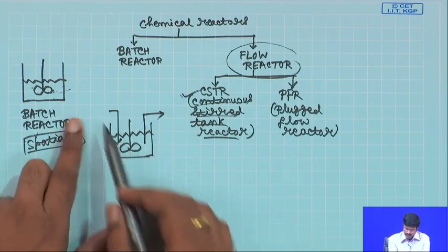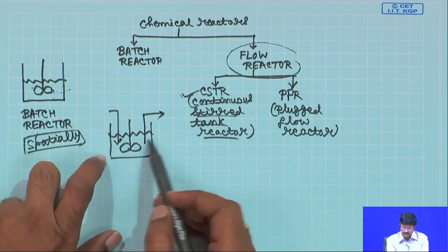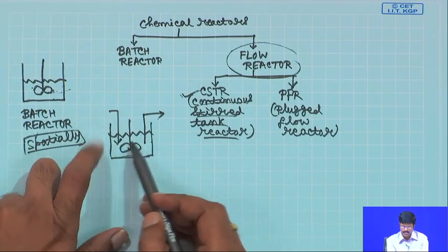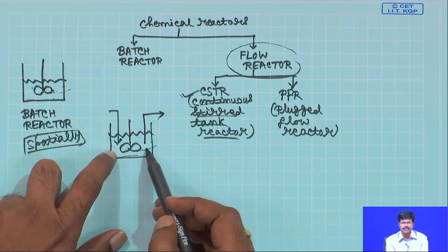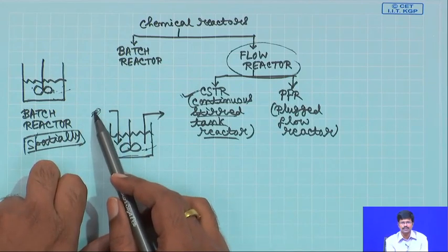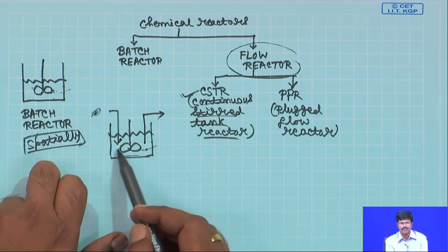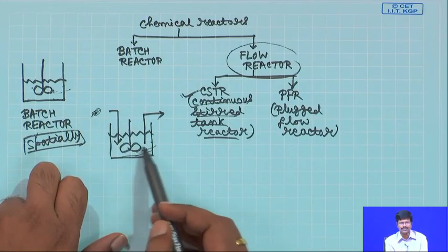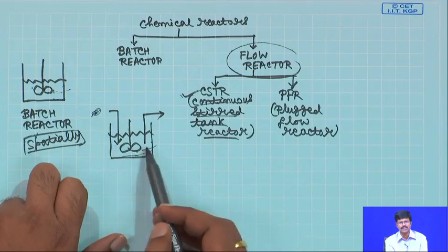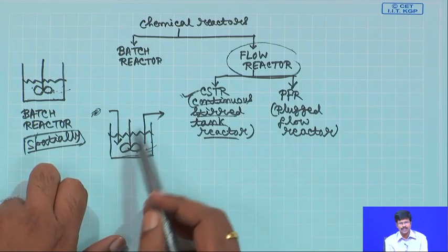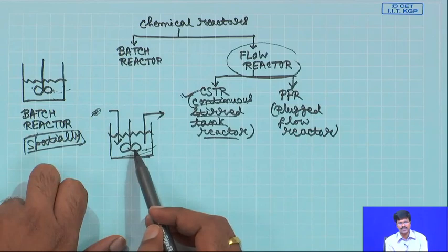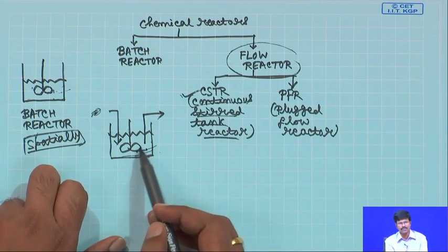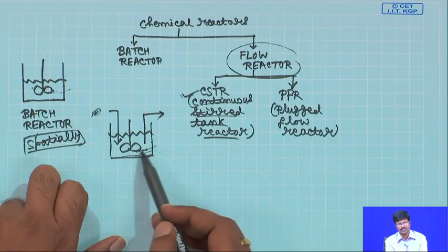So, what happens is that your reaction mixture is coming in and there is already a solution. So, the reaction mixture gets immediately diluted. You start with some concentration here, and when you put it here the concentration becomes much reduced because it is diluted in the reaction mixture, and that concentration throughout the reaction mixture stays the same, and if it is an isothermal system your temperature also stays the same as a function of time, it does not change, and whatever conversion you are having for a particular species, if you have a mixture of species, that conversion also does not change with time.